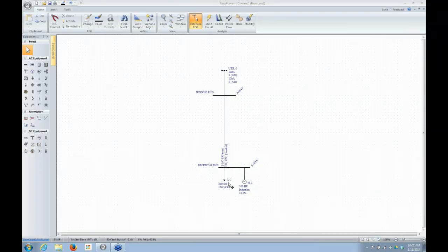So as this voltage changes, the kW or kVA or kVAR demand can change. But this voltage depends on the voltage drop between the sending and the receiving end, and that voltage drop depends on the current. But the current depends on the load, which depends on the voltage, which depends on the current. So the only way to solve this is to iterate, or trial and error.